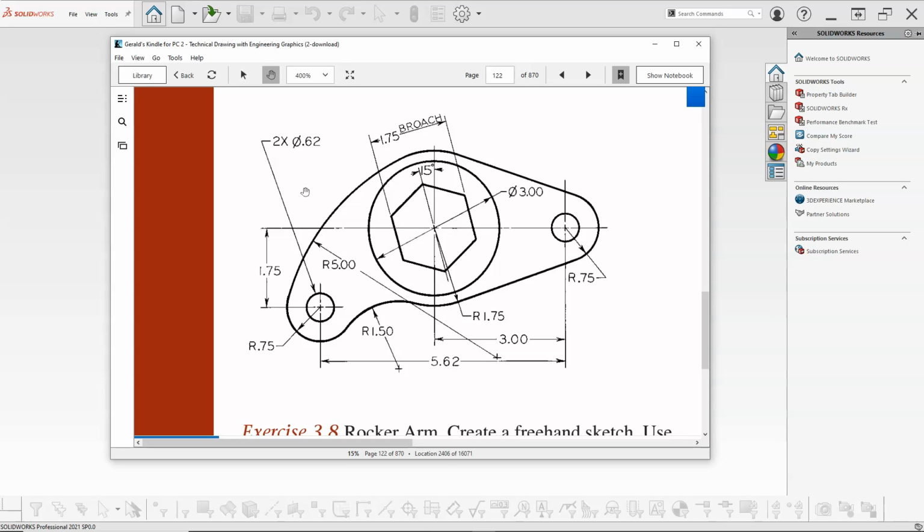So quick comments on the inch decimal: when we see 0.62, that should be something that jumps out at you, as that is a fractional 5/8, and if we carry it out, 0.625. If the process that we're working in is going to be that precise, if we're going to carry everything to 2 decimal places, then we should be fine. But in the assembly portion of this, if it comes down to clearances, interferences, that 5/1000ths maybe makes a difference.